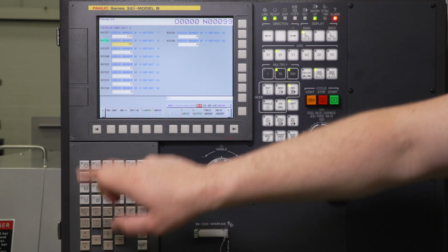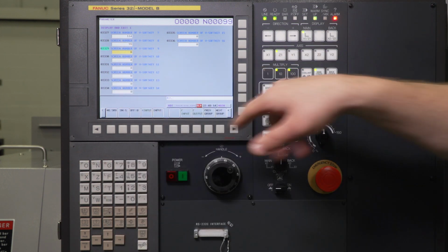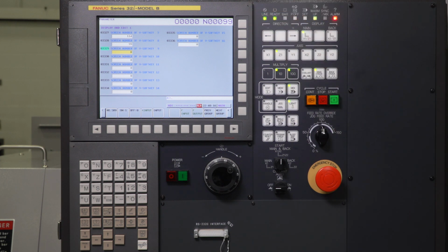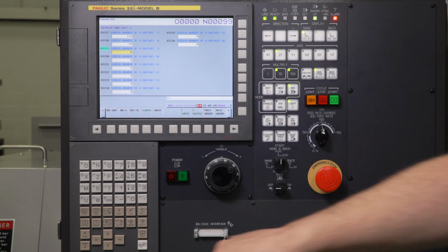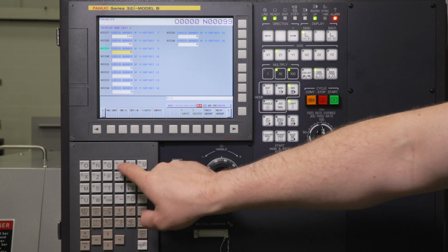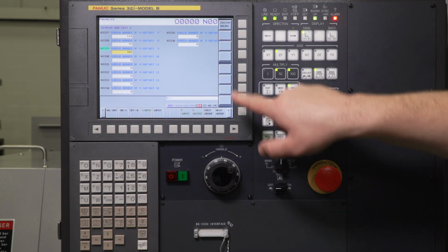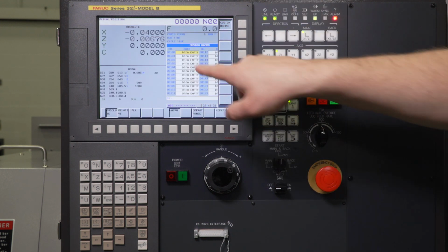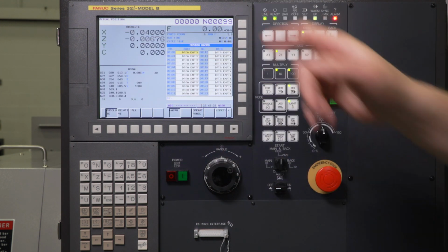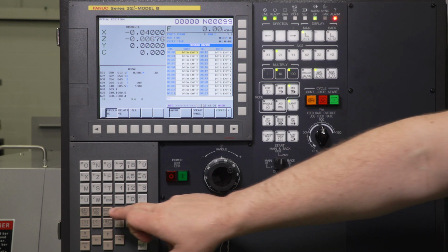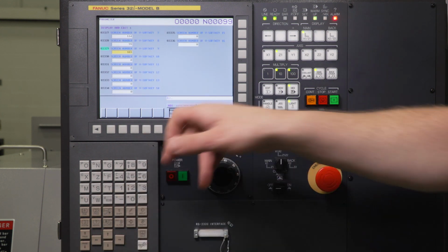So what we're going to do, now we have our second page. We're going to be back at the top here, and we're going to make that one the macro screen. So let's make that a 183 to represent the macro screen, input. And now we're on page 2, custom macro. It's going to bring us right to our macro screen. For those of you that use macro all the time, that actually saves you from a lot of key presses to get to the macro screen.